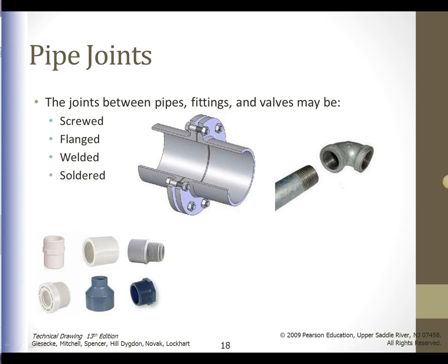Plastic pipes may be screwed together or fastened with slip joints or a solvent with compression fittings. The threads of the API, American Petroleum Institute, differ somewhat from the American National Standard pipe threads. Now, threaded joints can be made up tightly by simply screwing the cleaned threads together. However, it is common practice to use pipe compound to lubricate the threads, and this enables them to screw together more tightly. This compound also serves to seal irregularities, providing a tighter joint.